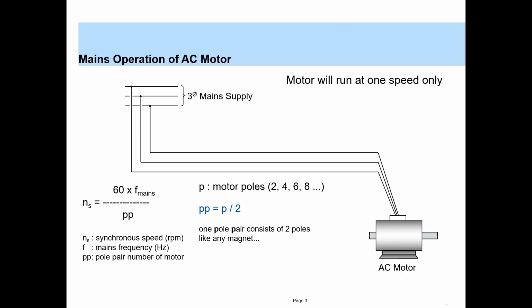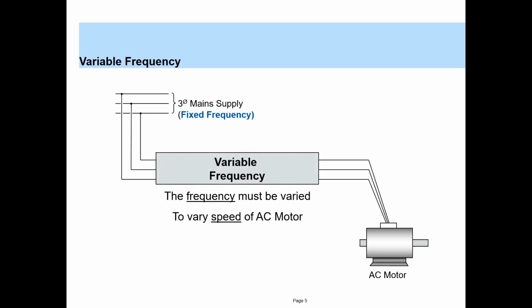So how do you achieve that? Use a drive, a variable frequency drive. What will happen is you can vary the frequency, as a result of which you can vary the synchronous speed, and hence you can operate the motor at 800 rpm. And over time, if you calculate, in a very short period of time you will see that the cost of this extra drive is outweighed by the energy savings that you have. Alright, so in that way, drives are very much useful.